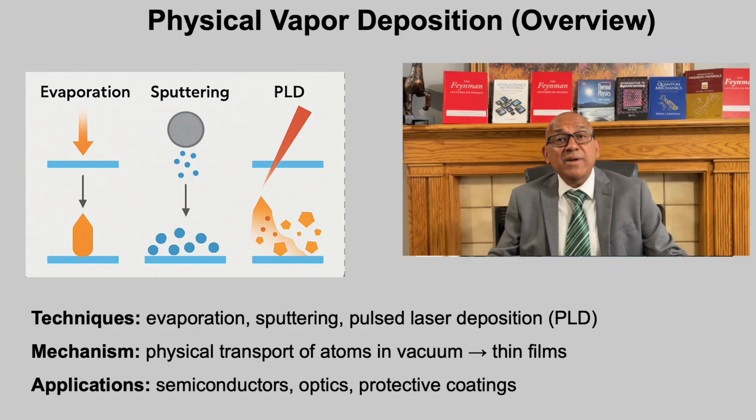The general PVD methods we will focus on are evaporation, sputtering, and pulse laser deposition, PLD. These approaches are versatile and widely used in research and industry, from depositing semiconductor layers to optical coatings on lenses and even hard coatings on tools.